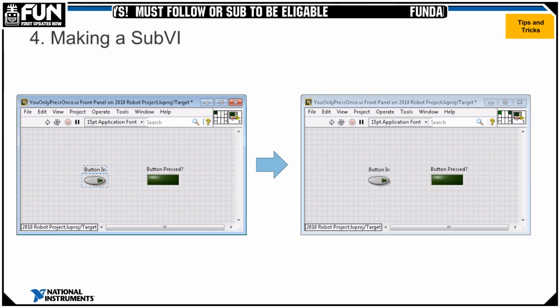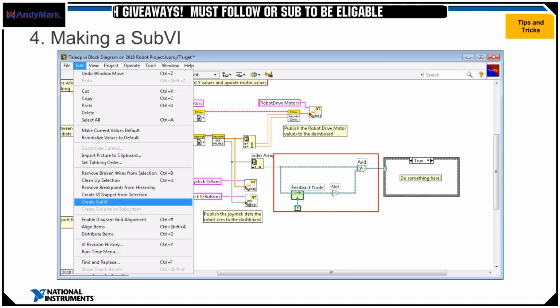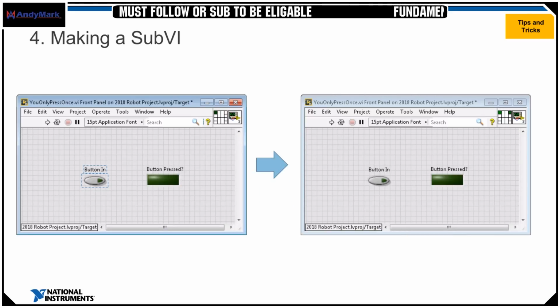We'll look at that a little more closely if it's a little confusing, but I repeat the process for my button pressed. I click in the upper right-hand corner, click on my button pressed indicator, and then those two are tied together. You can see that there are two little green squares in my connector pane now. Those represent my two Boolean inputs. Those colors are going to match whatever color your data type is.